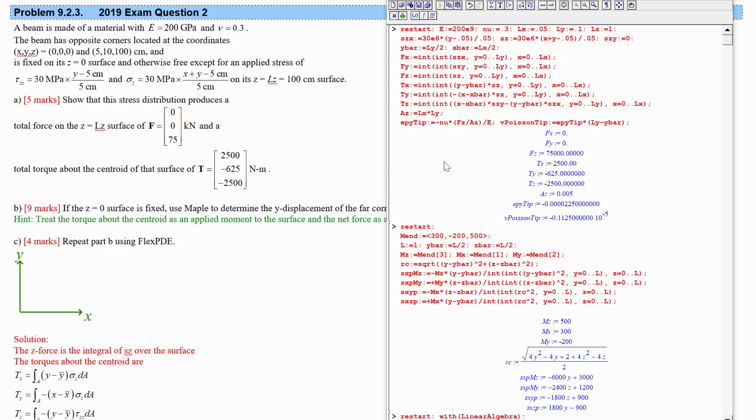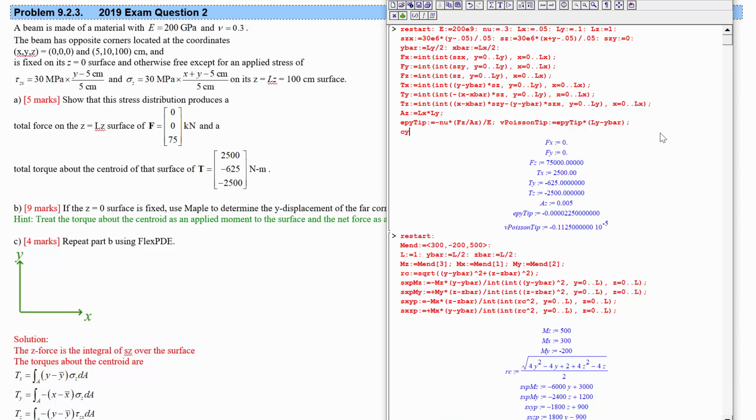What else leads to displacement at the tip? Well, in the y direction, it would be the x moment. The x-directed moment will lead to a curvature in the negative y direction. So the curvature in y is going to be equal to negative moment that we found in x. So really this is what we call torque in x.